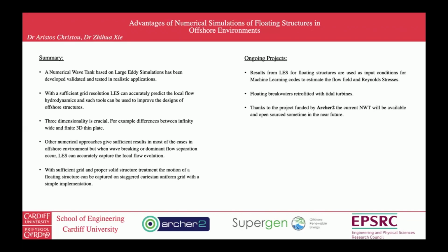Three-dimensionality is crucial, even though some cases seem to be two-dimensional. Three-dimensionality indeed exists. And large-eddy simulations with these specific sub-models, level set method, IBM, uniform grid, can be used to generate a complicated fluid structure interaction model.